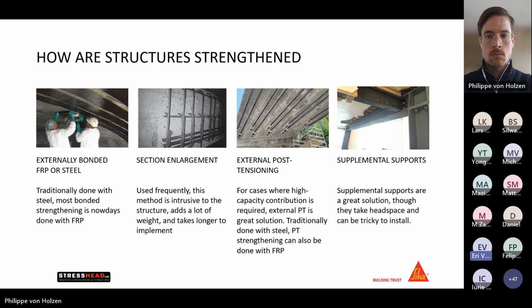One of them being that the existing structure has to be able to withstand some load. And if that doesn't work, there's always a possibility for section enlargement. Obviously, we know the disadvantages to it, which is adding a lot more weight, having to increase the cross-sectional area of the member, etc. In other cases, external post-tensioning is considered.